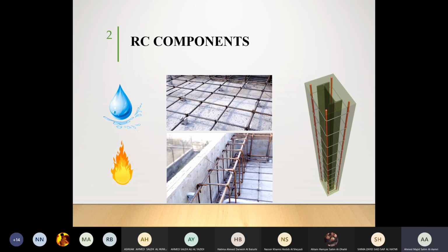Mister, but there is a building with a steel structure only. What should they do? It should be painted. Otherwise, it has a very high potential to fail if there is any case of fire. Okay. So normally, if you are seeing steel elements like this, they are either painted or the designer is having the responsibility for any fire case. But normally they will be painted. Municipality will not approve anything without having the steel columns or steel elements painted against fire.